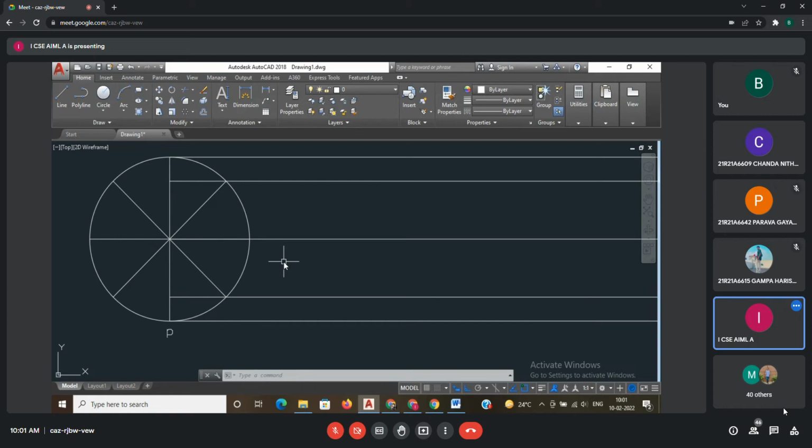Clockwise, sir. Means whenever the rolling circle rolls in clockwise direction, you have to take notations in anti-clockwise direction. That's it. Don't learn it by heart here. Even for epicycloid, hypocycloid also, it is the same. Don't confuse. We don't have any hidden thing in this. Just one logic: whenever the rolling circle rolls in clockwise direction, you have to take notations in anti-clockwise direction. That's it. Opposite. Now I will take the notations here.